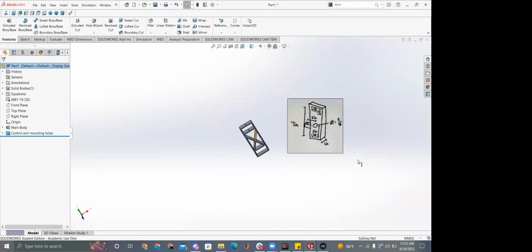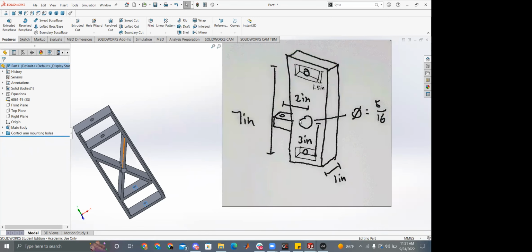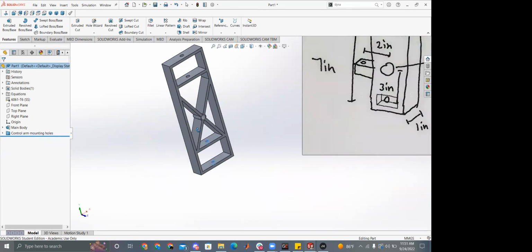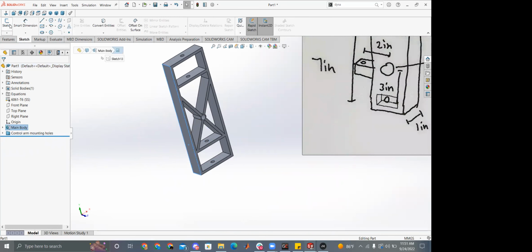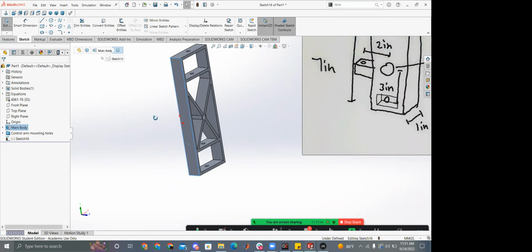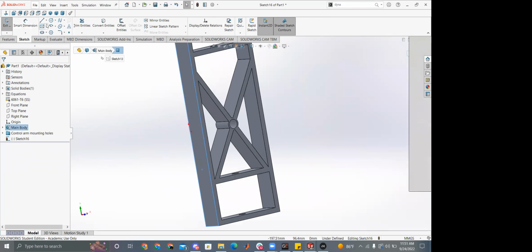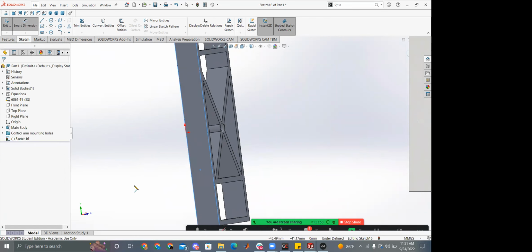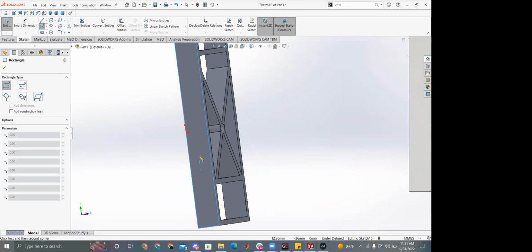So you'll notice in the sketch, this last thing here, this little thing is the steering arm. So we can make a new feature on the side to account for that. We did talk before about kind of reducing the number of features you have, but in certain cases where it's something that's really its own independent part, it's not a bad thing to have that extra feature just so it's easier to edit that thing individually. Like I could have easily had this in that original sketch on the main body, but it would have been a lot more difficult, a lot more time consuming to edit that steering arm if I only needed to edit the steering arm. So just like with everything, unfortunately, there is nuance. There is no one way best solution all the time.